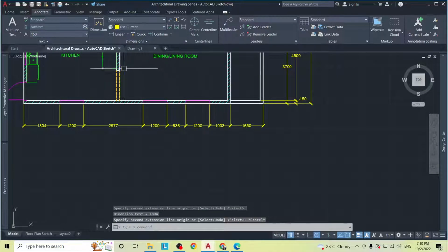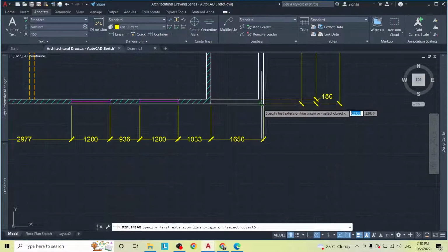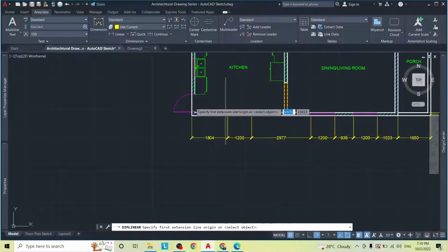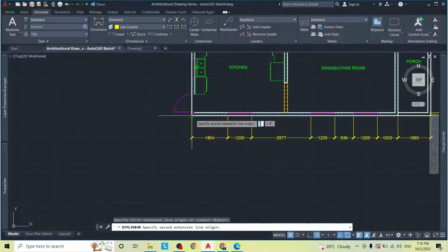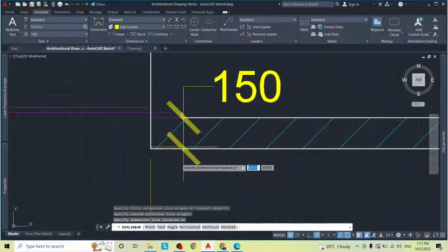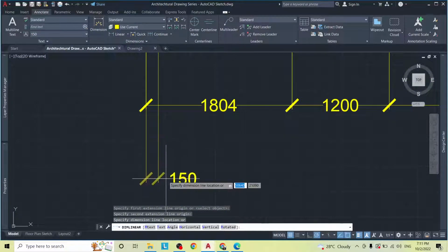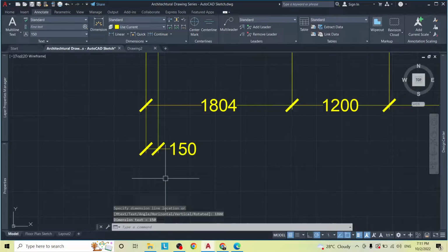All right. Walls and openings or windows. Now, the next layer is going to show the wall thickness. This one is a bit tricky for me. Let's try from this side because the porch is not technically the wall. So this one should be 1800.